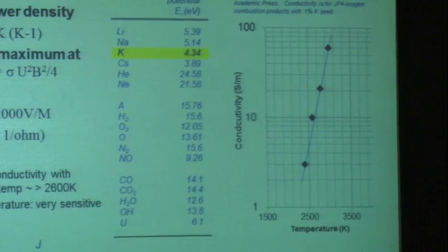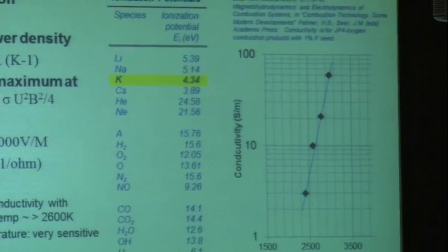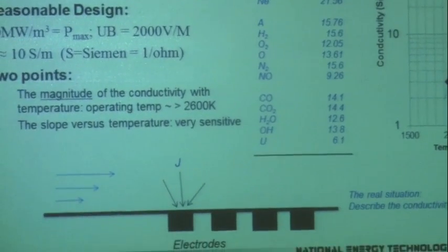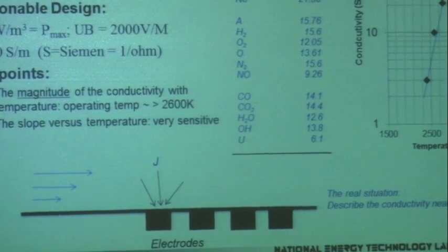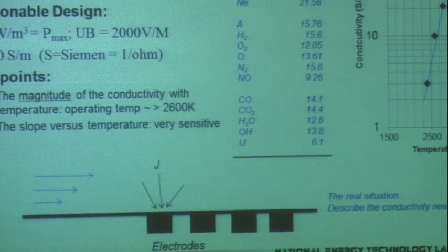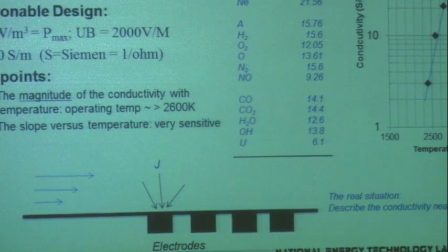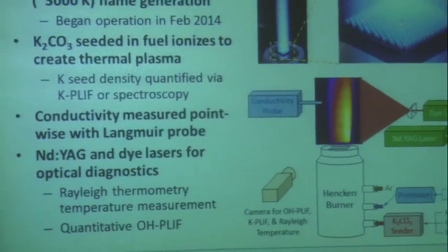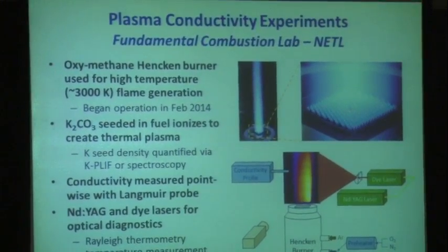That's why this idea of MHD only would make sense if you were doing oxy-fuel combustion, because you have to have very high temperatures, unless you can find some way to make the gas conductive that doesn't rely on thermal equilibrium of ionizing electrons off of the seed material. Let's keep going here. Well, it turns out we looked through some of the literature for conductivity from the earlier